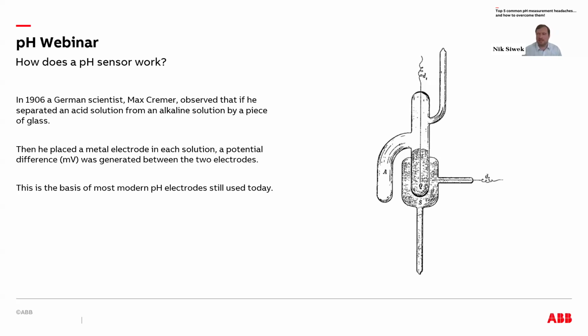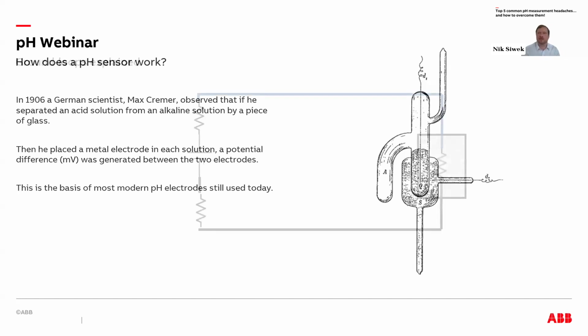We use the same kind of technology. But because we're dealing with very small millivolt values and a high impedance, or high resistance, glass electrode, there can be a number of different susceptible scenarios that make the output of the sensor prone to erratic behavior or readings that we don't fully understand.